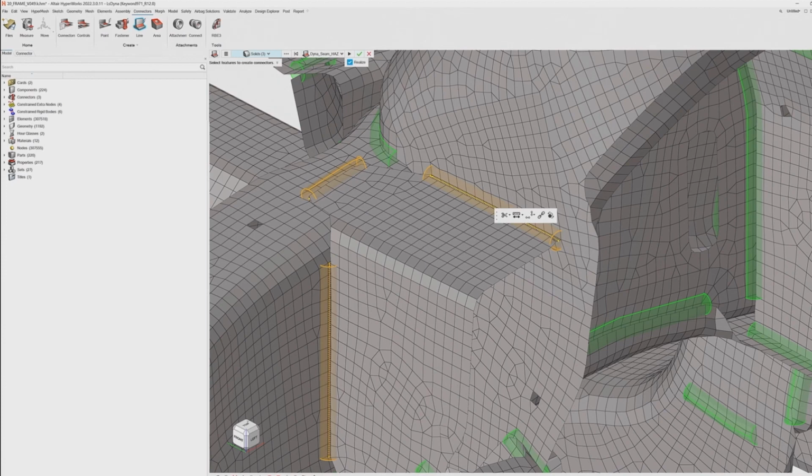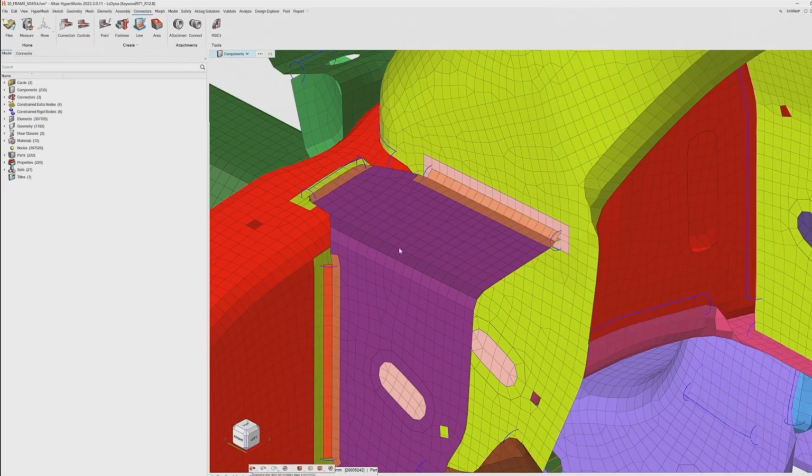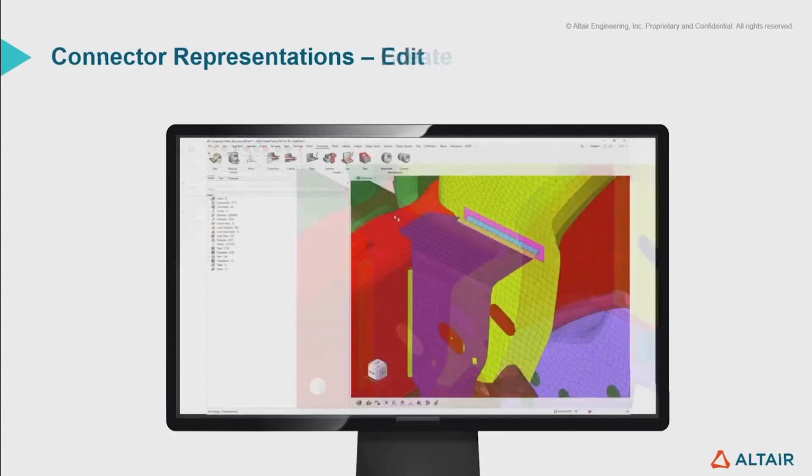Within the control for this particular realization style, you can define all of the things like how you want your heat affected zone calculated, what size you want your welds, what properties you want for the welds, what the calculation methodology is. All of those things can be done up front, and the angles for these particular ones can be defined within the control. So again, you can follow best practice from your analysis point of view in a very simple number of steps, and this historically wasn't really a usable or workable solution.